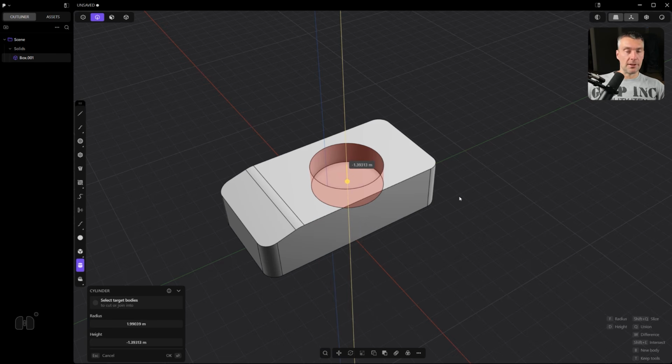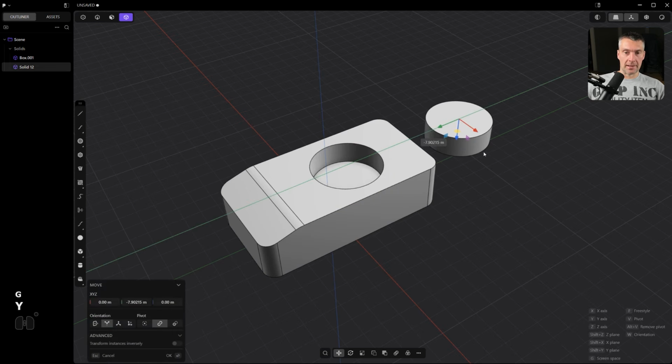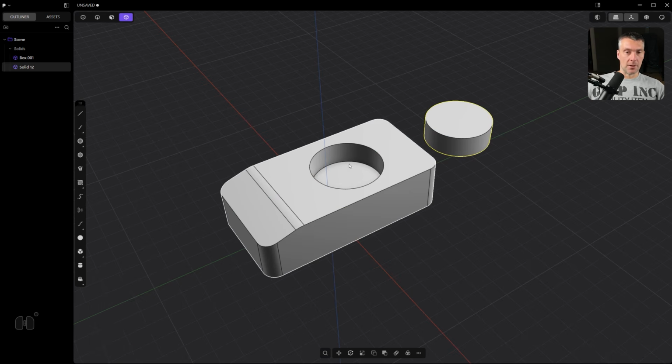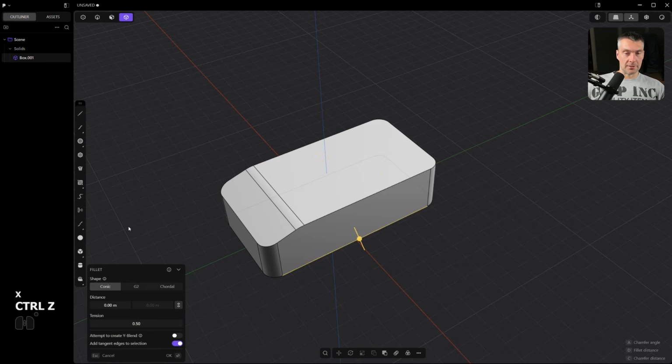So if you're going to press T, for example, or you're going to press B, for example, it's going to be performing different operations. So T, what it will do, it will cut this with a Boolean, but it will preserve the cutter, right? Just like shift click in HardOps with HardOps and Box Cutter. So if I press T and right click, it's going to approve it, cut my mesh, so press 4 for solids to move this, right? And see that we got this mesh preserved, this cutter, but we also have the cut. Now, if I'm going to just cut it and press B, something different is gonna happen, watch.